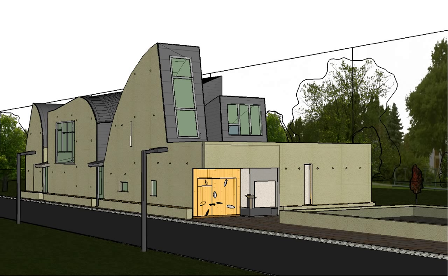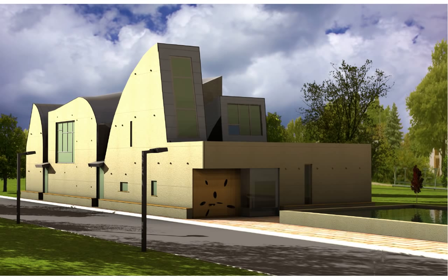What we'll do is we'll take the model that we have here, and we know how to render it for an exterior daylight scene, right? We're going to do the exact same thing we did with the previous model. You just add a sun, you turn on ambient occlusion and final gather. You can see a little bit of ambient occlusion that is subtracting and making it darker in the corners here. The final gather is bouncing light one time to globally illuminate the scene, and we're done. We're doing the same thing.